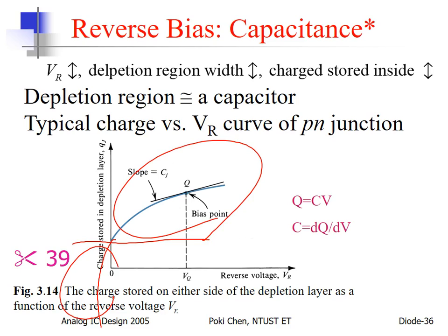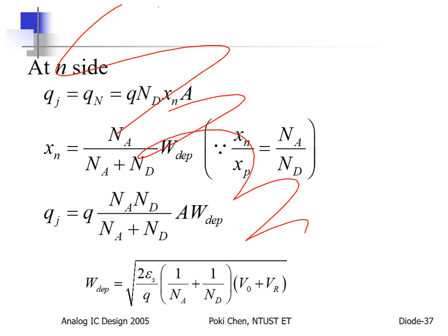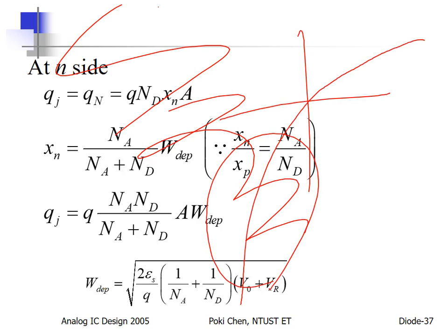Don't turn the diode on and off. You turn on and turn off. Yeah, the charges, especially when it is forward bias, millions, billions of charges need to be pushed to the other side. If you want to turn it off, you need to pull them back. It takes a much longer time. Okay? So, again, according to what I told you, don't operate your diode here and there very frequently, because the operation frequency will be slowed down very, very much.